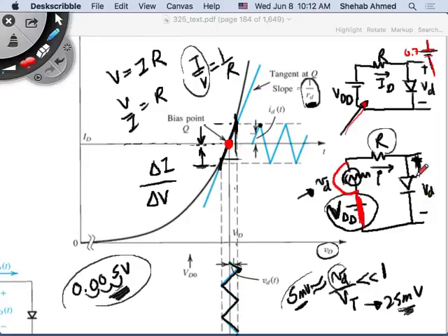No, I cannot put the reverse supply here, this reverse supply is 0.7 volts. This thing is 5 millivolts max. So what do I do? Because I want to use superposition. For superposition, it has to be linear. Linear means this cannot be very large. We limited it actually to 5 millivolts. So I have to find a way.